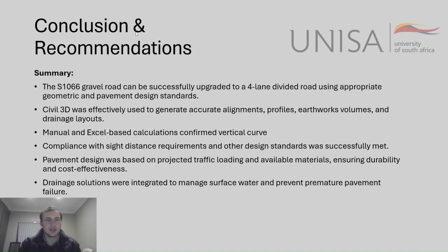Conclusion and recommendations. In summary, the S1066 gravel road can be successfully upgraded to a four-lane divided road using appropriate geometric and pavement design standards. Civil 3D was effectively used to generate accurate alignments, profiles, earthwork volumes, and drainage layouts. Manual and Excel-based calculations confirmed vertical curve. Once again, to check what I've received from Civil 3D there. Compliance